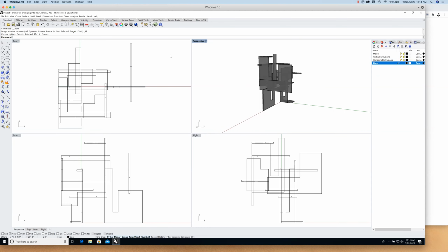There's a couple of ways we can begin to think about surfacing that will help with this. First, I'm going to pull out all my surface creation tools here. Again, if you look at the toolbar, we make points. We can use points to make curves. We use curves to make surfaces, and then there's how to make all the surfaces. I click and hold, and a whole bunch of surface creation tools pop out, and I can pull those over. Let's take a look at these really quickly. I can create a surface by snapping and defining some vertices, like 3 or 4 of them, in order to make a triangulated surface or a quad-shaped surface.